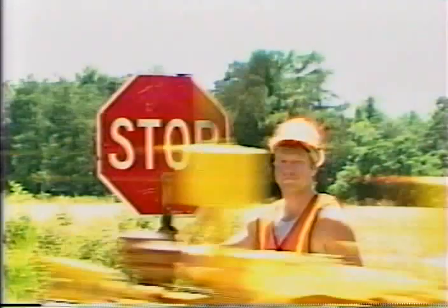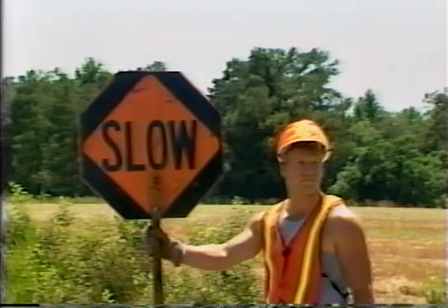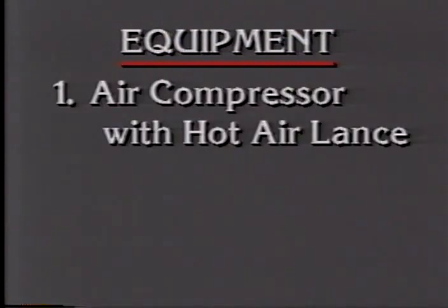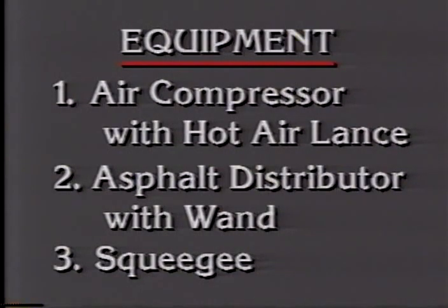With proper traffic control in place, the crack sealing operation can begin. The equipment needed for crack sealing includes an air compressor, preferably with a hot air lance, an asphalt distributor with a wand applicator, and a squeegee.